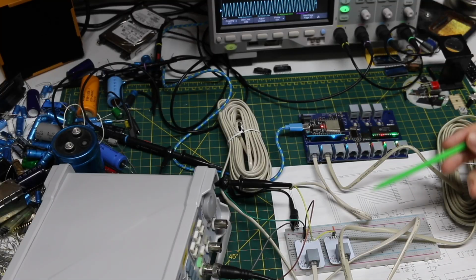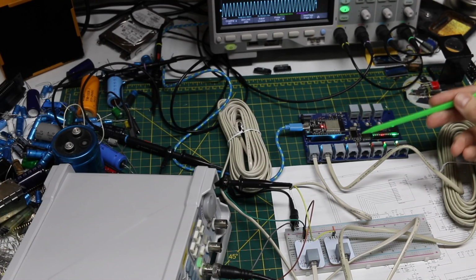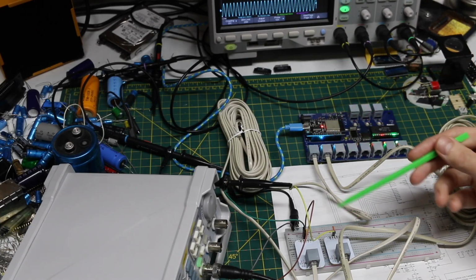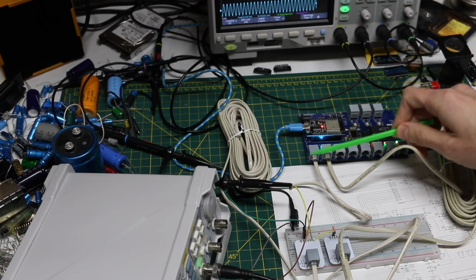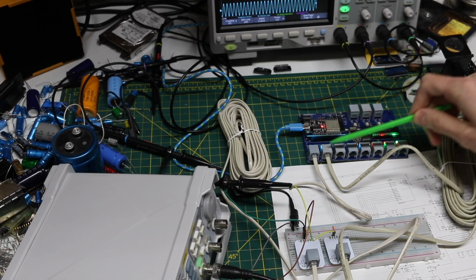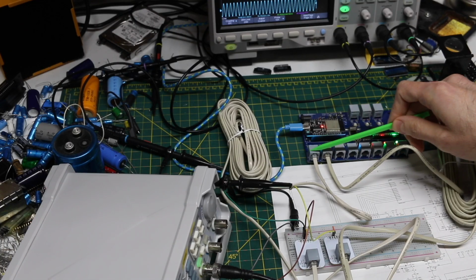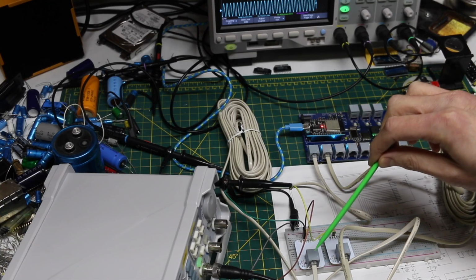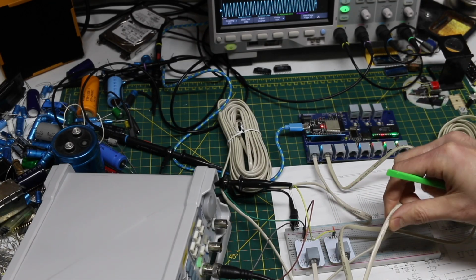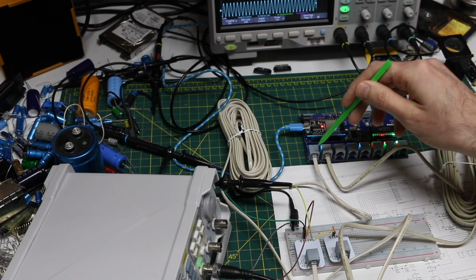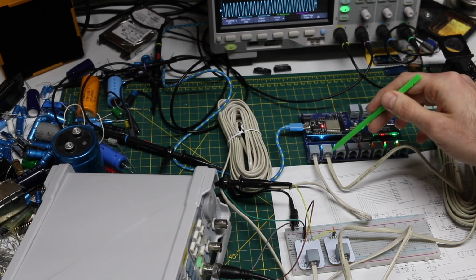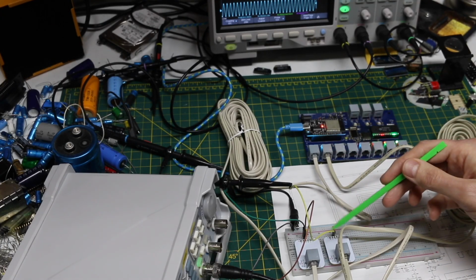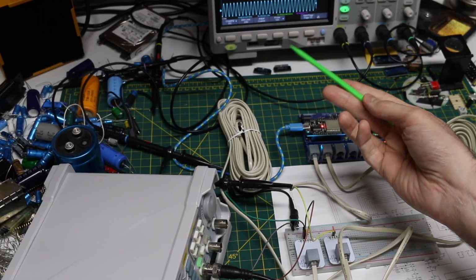Here's a test setup to try out the board. And I can't fit everything on screen, so I'll just explain the overall part and then zoom in toward the scope. I have two phone cables to go between various phone jacks. One of these is being fed with a sine wave from a signal generator through a phone jack on the breadboard. So the cable comes around to this bundle and plugs into this first jack. Then the second cable here comes over to another breadboard jack, and that just goes to a scope probe so we can see what's happening.